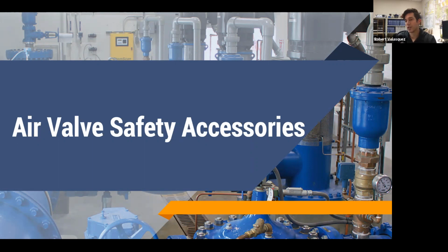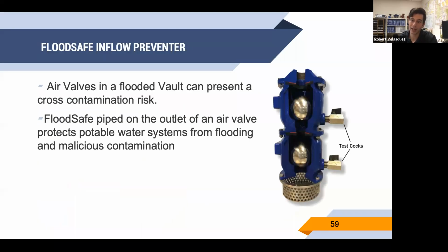So another way to do it is that we would pipe a pipe out of our vault up to the surface, and then pipe around our air vacuum valve and provide an air break. So you can get air out of there, but air won't come in. And a way to prevent cross-contamination is to then put an inflow preventer. An inflow preventer is a double check assembly that will connect to the exhaust of an air vacuum or combination air valve. And if your vault floods and it fills up with water, it'll raise up the balls on this and that will close off the path. So now you won't get water cross-contaminating into your system.